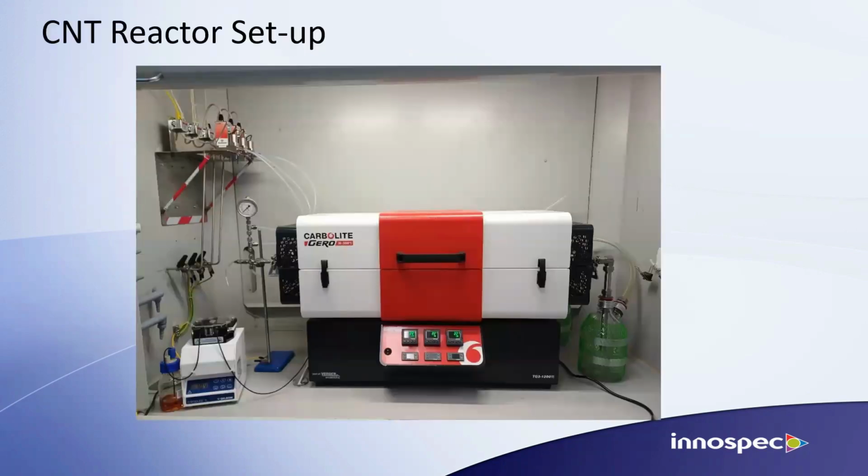So here we have an image of our horizontal chemical vapor deposition reactor setup. The furnace has 3 temperature zones, which can be individually controlled, giving flexibility in managing the carbon nanotube growth. Depending on the desired experimental conditions, inert carrier gases and/or reducing gases can be employed, and the flow rate of these can be adjusted to tune the process as required. So far, we've not used any gaseous carbon sources and only focused on liquid carbon sources for ease of use. The system can be operated using either direct injection or solid-state catalyst delivery, allowing process flexibility.